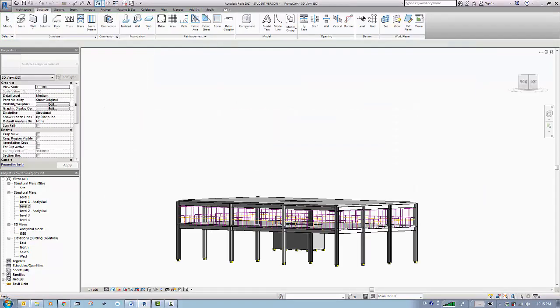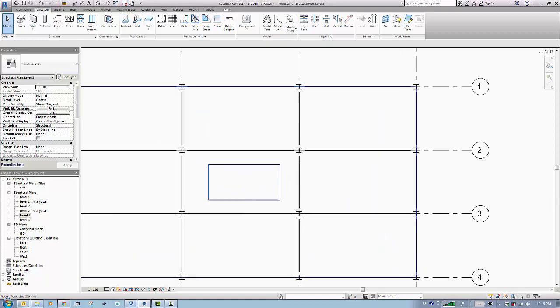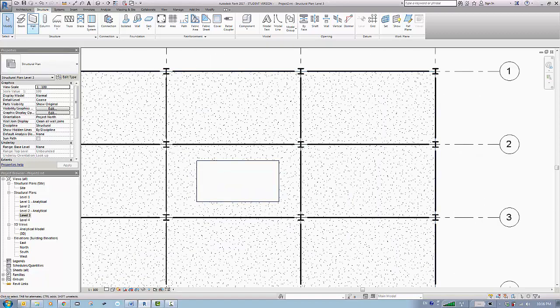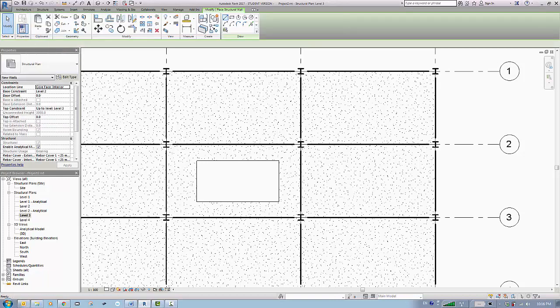So it should show this. Of course, this level has been copied with the loads. That's the good thing about it. Now I need to do the walls, like I said. For the walls, I go to Wall, Structural Wall, and the shaft wall type is still valid. I go with Pick, and here it says Core Face Interior, so we'll choose the shaft surface lines to create our walls.